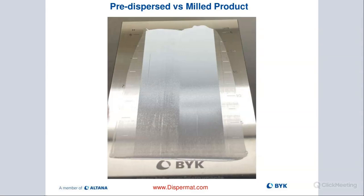When we continued the process and we started the media milling, you can now see the product looks much better. It's basically a Hegman grind gauge, and we're able to just really visually see a difference between the two. So it's imperative that we don't stop just using a blade, that we actually use a media mill if we want to have a much better looking product.